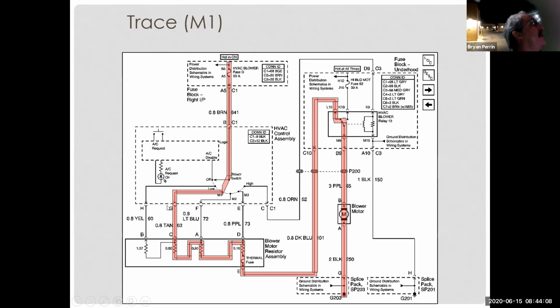But if I come down through here, this is connected, isn't it? So I would have voltage come back through here, all the way to right here. So this would all have system voltage because I can't drop any voltage across that resistor. It's an open circuit. This is why people get confused when they're testing electrical things.